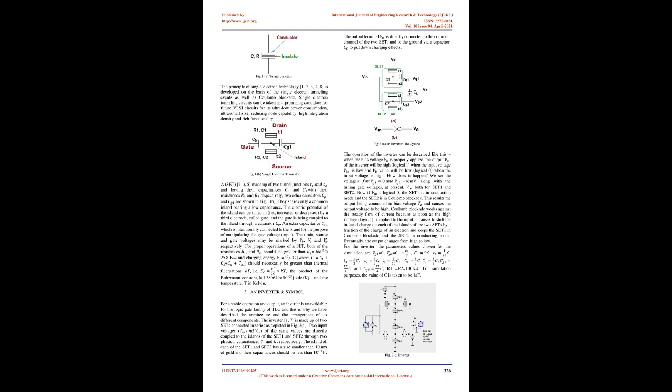When two conducting materials are connected together with an insulating layer between them, there will also be a capacitance in the junction. In this context, the insulator represents itself as a dielectric, and two conducting plates with the dielectric form a capacitor C in the tunnel junction. Due to the discrete nature of electric charge in the tunneling phenomenon, current flowing through a tunnel junction is discontinuous, i.e., a series of events in which merely one electron will be able to pass or tunnel through the tunnel junction at a particular time. Owing to the single electron tunneling through the junction, the tunnel capacitance is charged with an elementary charge, 1.60217662 times 10 to the power minus 19 coulombs, developing a voltage according to the relation V equals e over C, where C equals tunnel junction capacitance.